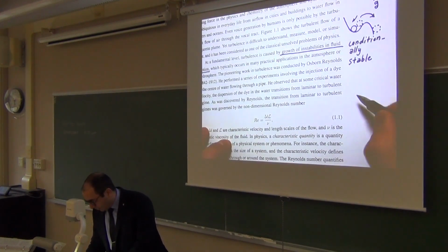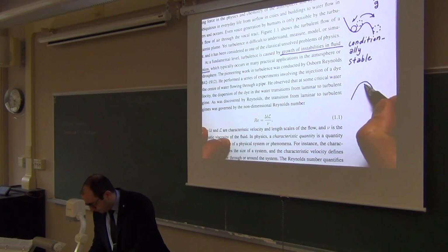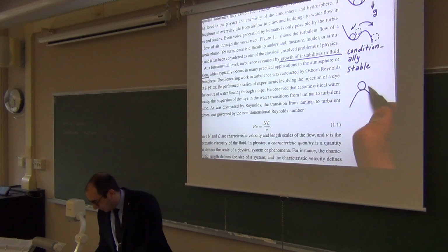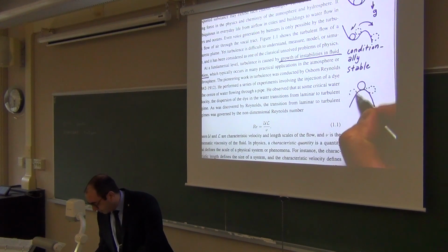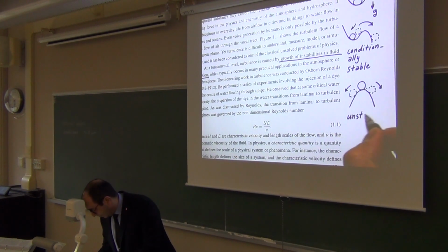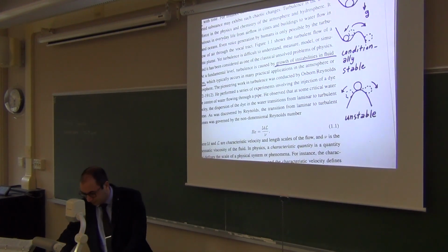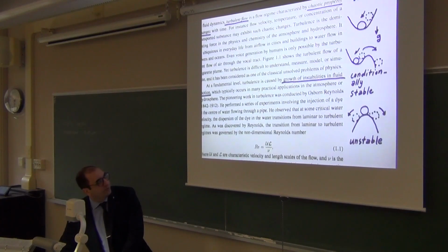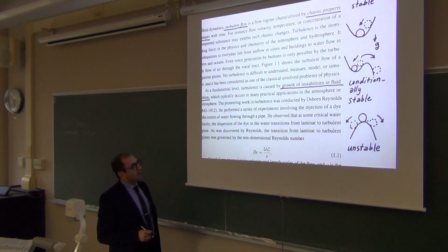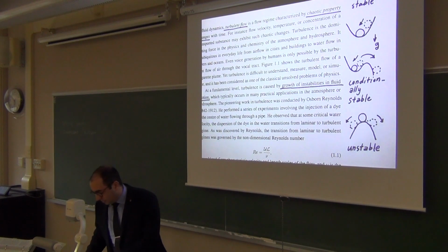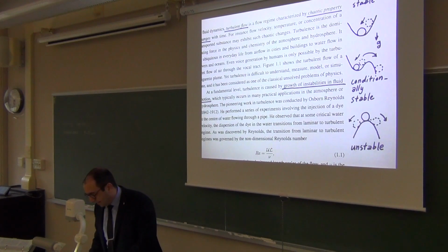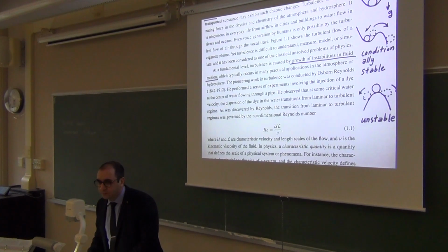But there are other systems that are unstable 100%, right? If you put this ball on the top of the hill, then whatever bit of perturbation it experiences, it is going to fall down. This is for sure an unstable situation. So when we say turbulent flows are flows that are unstable, some sort of instability grows in them, right? These flows experience perturbation. There's a boundary condition that's moving. There's something that causes the flow to change, and that always is in the direction of growing instability.